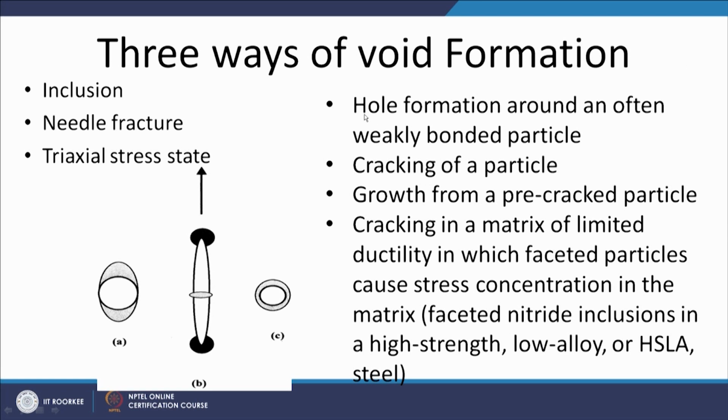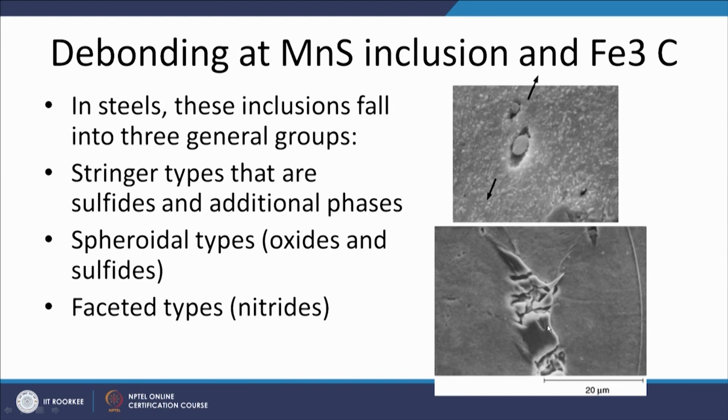So, it basically is void formation often around a weakly bonded particle. This can also happen when cracking of the particles takes place, growth of pre-cracked particles, or cracking in a matrix of limited ductility in which faceted particles cause stress concentration. So, the presence of all these hard particles will lead to the formation of voids.